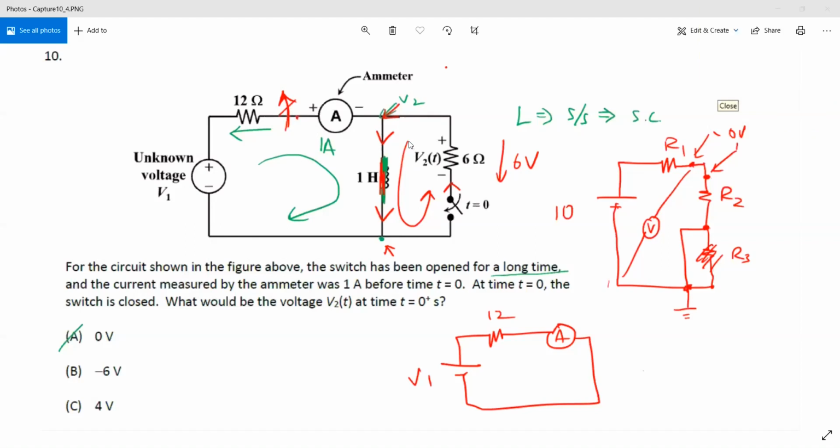But I thought that because the switch is open at the top here, and there's no current powering through the circuit, the inductor acts as an open circuit, because there's no build-up charge. Correct, but because there is current flow for an inductor, the current flow through the inductor cannot change instantaneously. It has to decay.